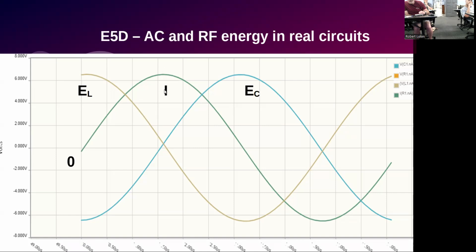the sharing. If you plot voltage versus current for an inductive reactance and a capacitive reactance, you can see the positive phase shift and the negative phase shift. So these are 90 degrees apart, which means EL and EC are 180 degrees apart. And if they were equal, what would the result be? You would cancel each other out. Right. If they're not equal, then you're going to have a phase shift one way or the other.